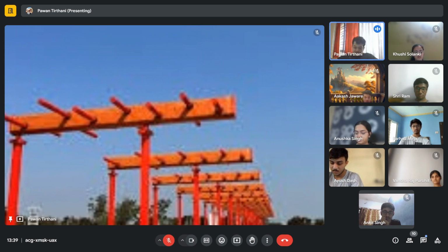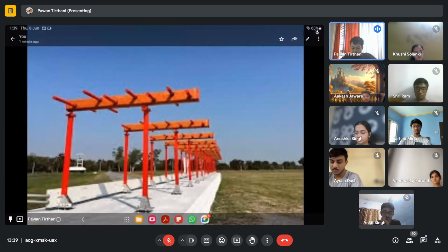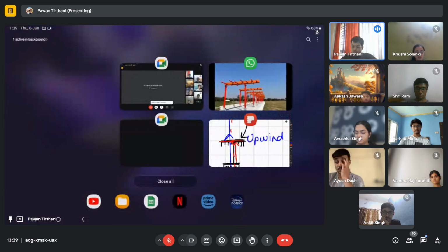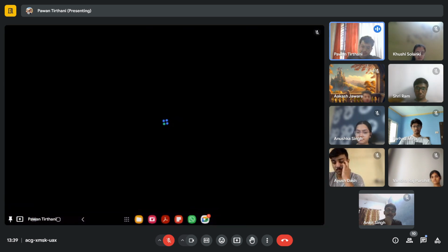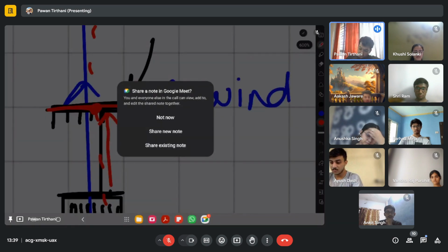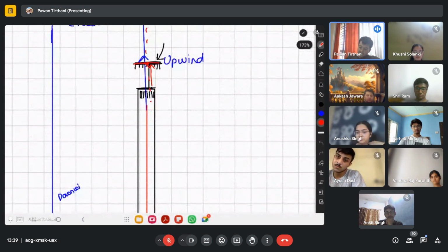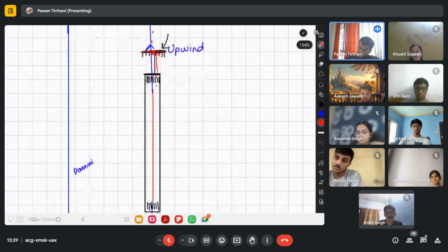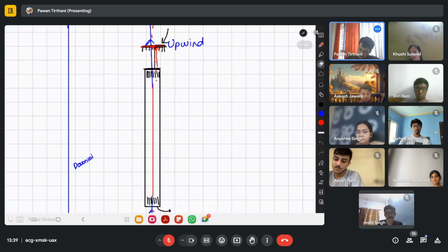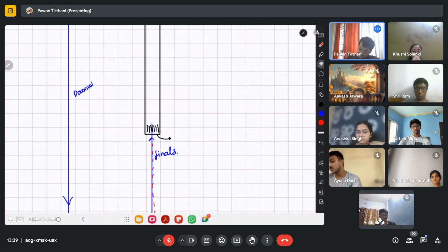The energy is being directed, and they are transmitting radio waves in the form of a lobe, not one lobe, two lobes. As I've told you, it's multi-channel analog information. So the two channels that we have are this. So this localizer antenna is transmitting two lobes.